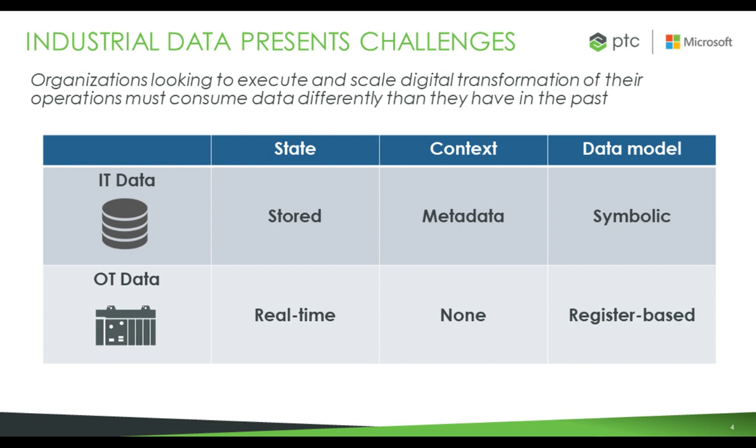You can contrast that to OT data, where the data coming off a PLC is real time. If you're not capturing it when it's created, then it's gone forever. On the other hand, you can't capture all of that data and just drop it into a SQL database or even a time series database, because some of that data is changing every 100 milliseconds. The factory is awash with data, and your storage bill would be astronomical. So you still need to store a lot of that data, but you need to be very smart about what data you need when and how it rolls up into critical KPIs.